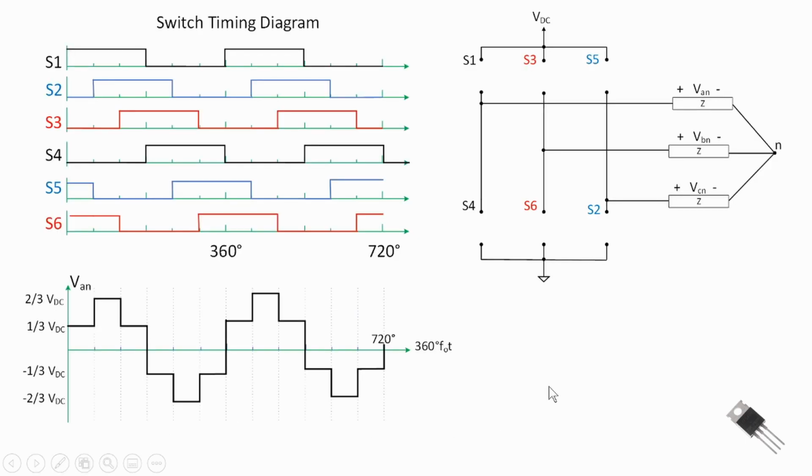And also go back in part 1 of these videos, we showed how to create this waveform down here, and that's our modified sine wave from a 6-step, and we see the 6 different steps here, S1, S2, S3, and those correspond to the logic levels associated with our switching on our 3-phase half bridge over here on the right-hand side, connected to our Y-connected load.